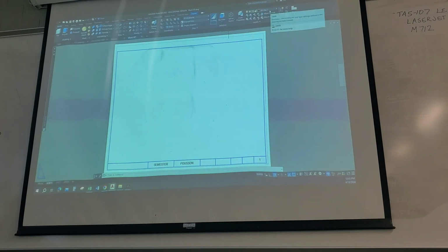You can change to a particular layer if you want to, but I usually just keep it in one of my same 3D layers. We've got this command over here called the base command. So I'm on my 3D ribbon in AutoCAD, on the home tab. All the way down here at the end, we've got the base command. When I click on that and expand that command, you'll see that we've got two options there. We can either bring that 3D object in from AutoCAD's model space, or we can bring that 3D object in from Autodesk Inventor. So in this case, we're going to be bringing it in from model space.